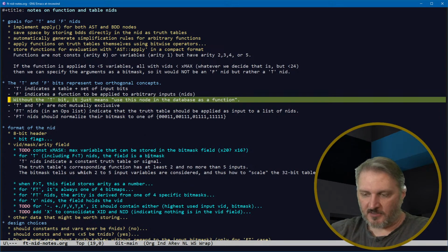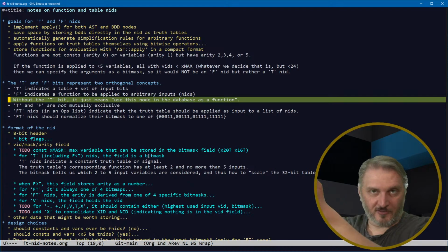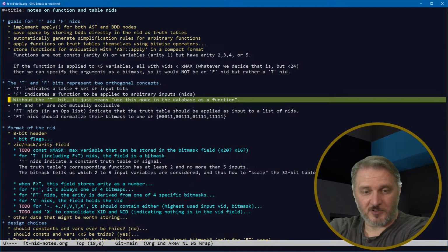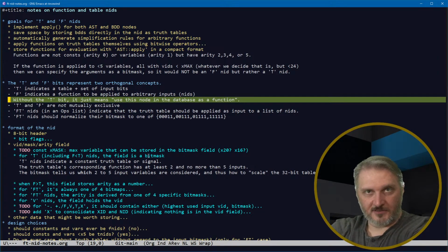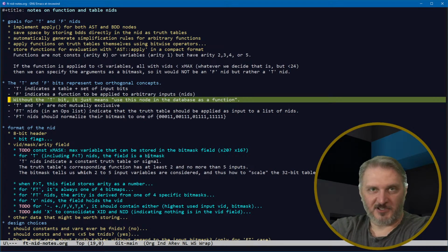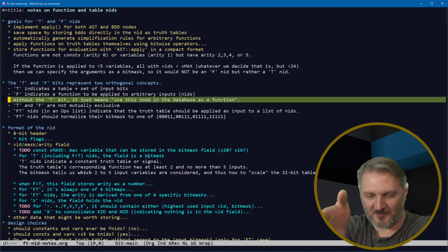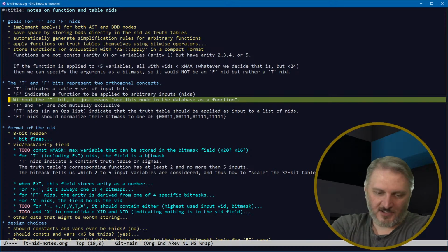So here you've got the rightmost bit has two inputs. The lowest output bit had two inputs when you do multiplication, right? An even times an even is even, an even times an odd is even, and an odd times an odd is a one. So you only had to look at those last two bits of the inputs to find out what the bit of the output is, right? But then for the next bit you have to worry about those first two input bits and the second two input bits, the second column of input bits, and so on.